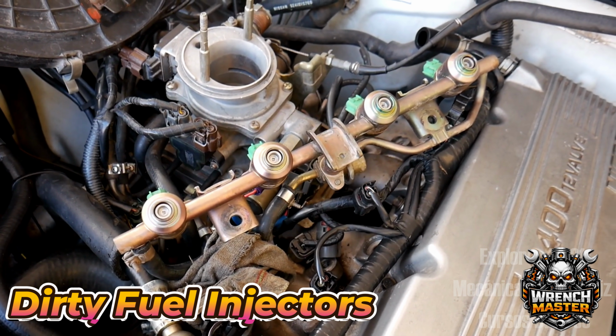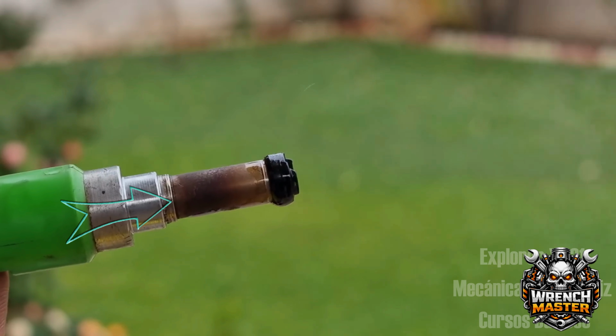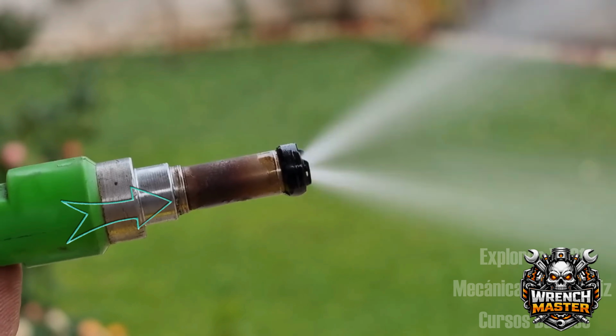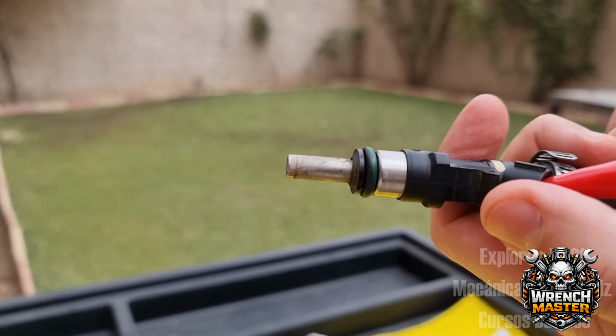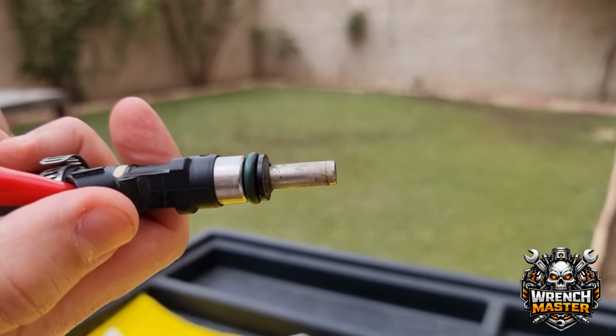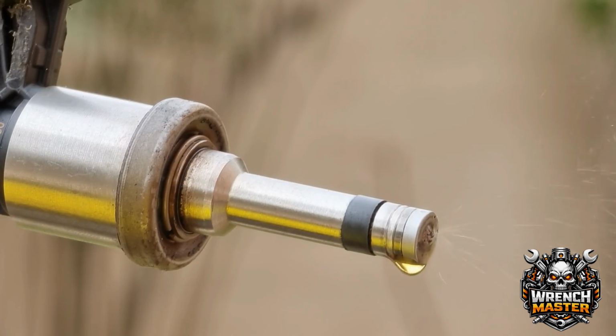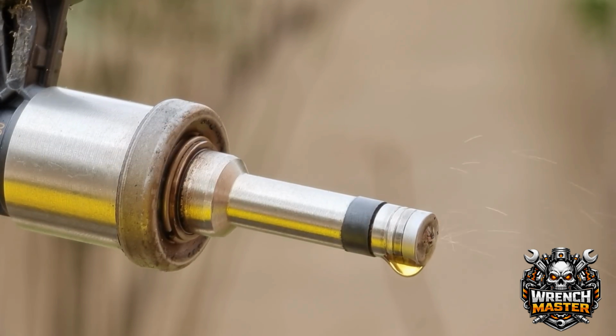Dirty fuel injectors. Fuel injectors are one of the main causes of excessive fuel consumption because when they are dirty, they can inject more fuel than commanded by the ECU. This occurs because the injector may have poor atomization or may remain partially open, causing uncontrolled fuel delivery.